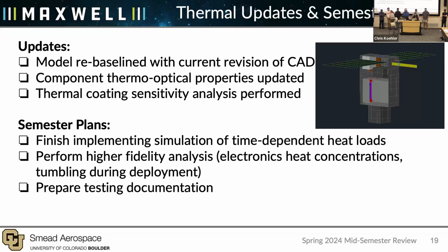Okay, so for thermal updates, if you see the model right there on your right-hand side, we are done with updating the model with the current revision of the CAD model from the structure team. And then we are done with component thermo-optical testing, with properties updated in the table that is in line with the thermal model. And then we are done with thermal coating sensitivity analysis.